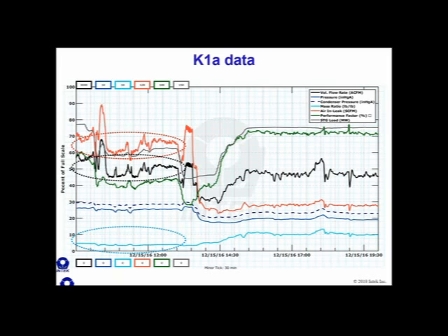So with this data, we can tell, number one, their vacuum pumps are pulling what they're supposed to be pulling. Their air in-leakage is high. They did not have any methods for monitoring air in-leakage. They had some pretty poor condition rotometers on their vacuum pumps. And so they didn't know if it was vacuum pump capacity related or air in-leakage related. So immediately, right after you get the Reovacs in line, you can see that pumps are working well, air in-leakage is high, and they've got a problem here. So we conducted a helium survey here.